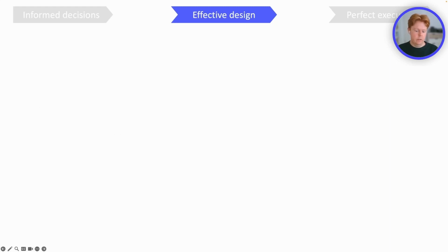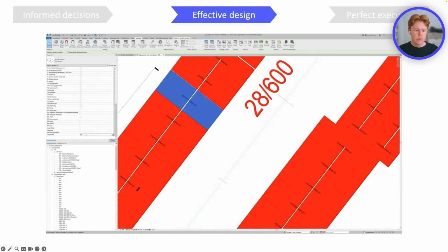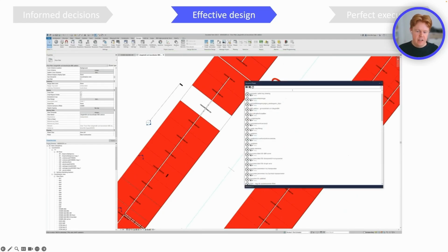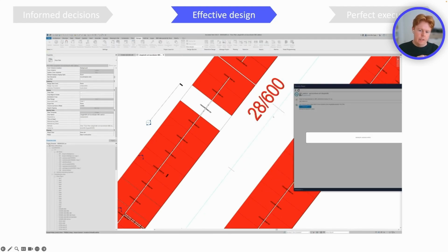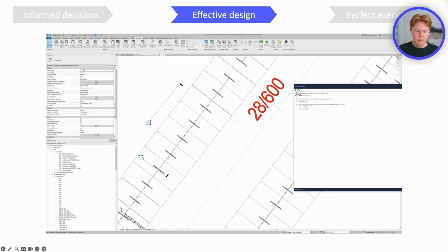So the first one here, just to set the scene: sprinklers are modeled in sections. Every section has a size and a number of sprinklers connected to it, and it is important to know where this section is in the world and in the model. Here you see them in red, which means they have no information on them. When you add information, they turn white. We're using Dynamo Player here to select the measurement that we get from the builders, and then it can read that and figure out where this section is in the world.